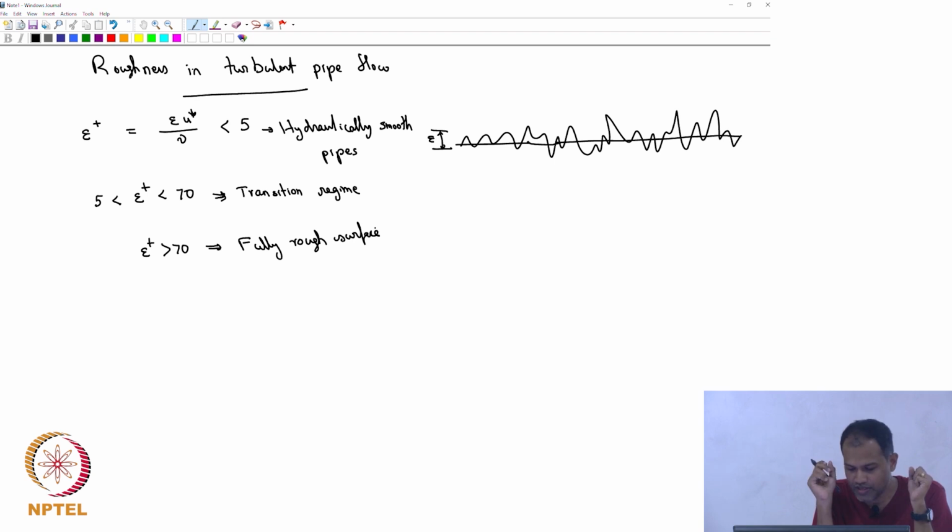So it's some classification. You can say that on one limit you basically have very smooth pipes, and on the other hand you have very rough pipes, and in between, anything that could vary, you basically have a transition regime. And as usual, just like in the flow, here also if things are in between smooth and fully rough, calculations are harder, and that's why this classification. Is that clear?